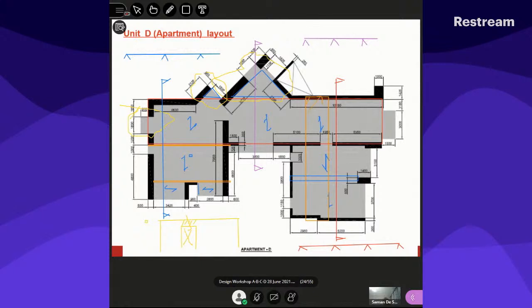So this is the slab design I'm now looking at. All the beam designs are basically simply supported beams. They are very deep where the walls are. If you introduce a beam like this blue color one, which I am just drawing over, you have to size it using span to depth ratios and then analyze it as simply supported at both ends, and design this particular beam carrying the catchment areas and things like that.